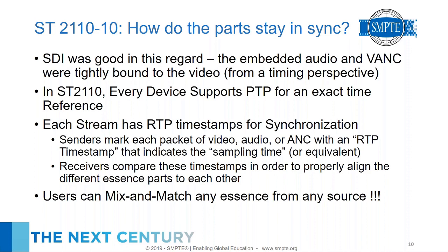And the nice part is, because the VANC is now a separate data flow, you could have a producer or consumer of those messages simply generate them onto the network with correct timestamps, instead of today where you have to have an SDI inserter that takes the main channel feed, loops it in, adds the one more trigger, and loops it back out. Once we go to having separate flows for these VANC signals, it really is liberating in the plant design, because you can stop looping your air chain through a bunch of inserters and simply assemble the signal you want.